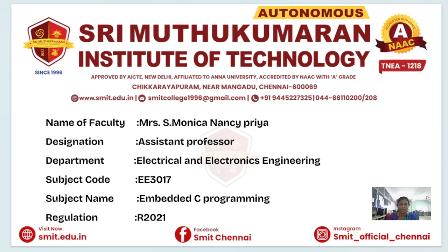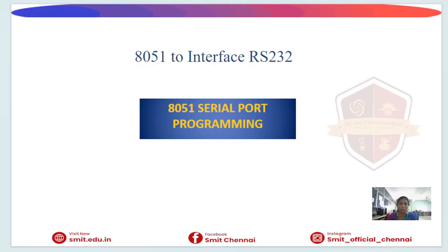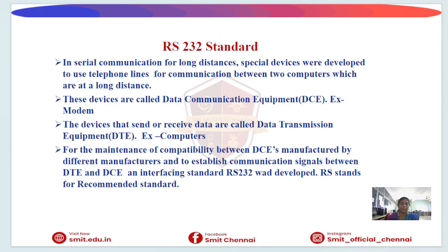In this session, we are going to discuss the serial interface of 8051 with RS232, that is, 8051 serial port programming. In this first part, the interfacing of the 8051 microcontroller with the RS232 communication standard: the 8051 microcontroller communicates using serial communication only. To communicate with computers or external devices, the RS232 protocol is used. The important components in this interface are the 8051 microcontroller, RS232, and the MAX232 IC.